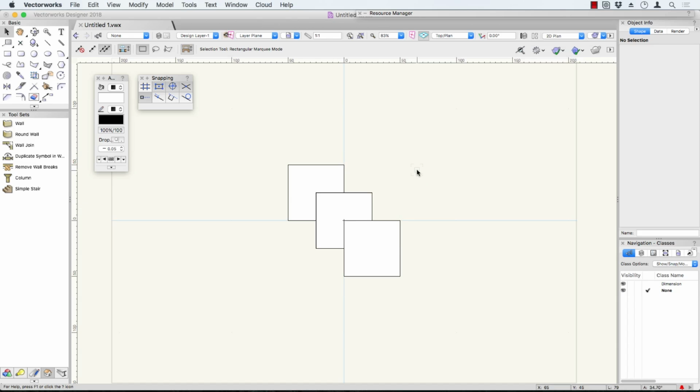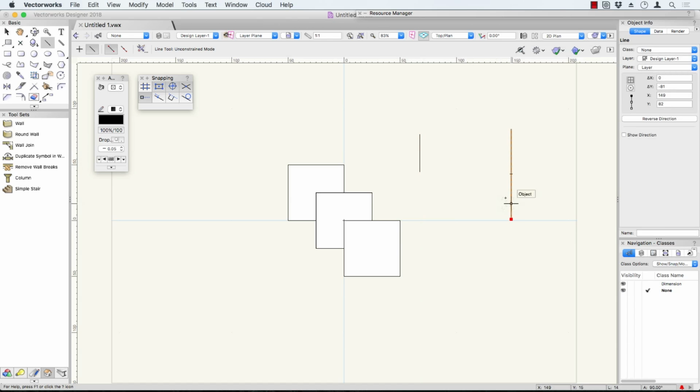Also I can snap halfway between those two. So if I've got a line over here, choosing my line tool, and a line there, I need to mirror something, and I need to mirror it exactly halfway. What's an easy way to do it? Using the mirror tool, touch that point there, touch that point there, and exactly halfway in between I get a little vertical bar. There it is, that's my midpoint. So I can draw a line midway between those other two. I can get rid of that now.